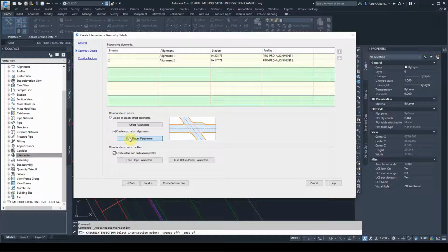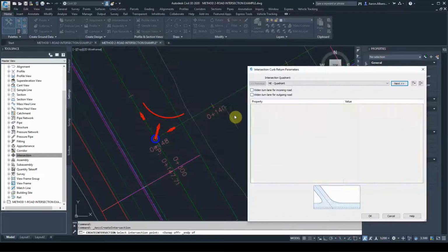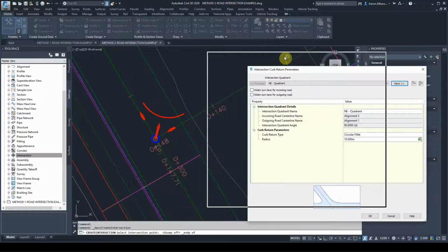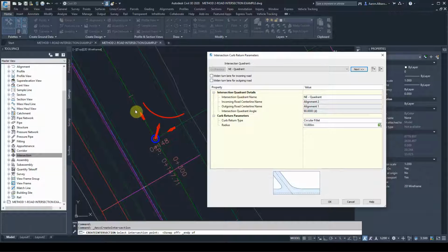And for the curve return settings, again asking us here for this curve return, it's worth noticing Civil 3D chooses the direction always clockwise too. So the direction here, the rotation is clockwise, as you can see. Keep that in mind, we will need it down the track. And the name convention is very similar to what we chose in our previous video.